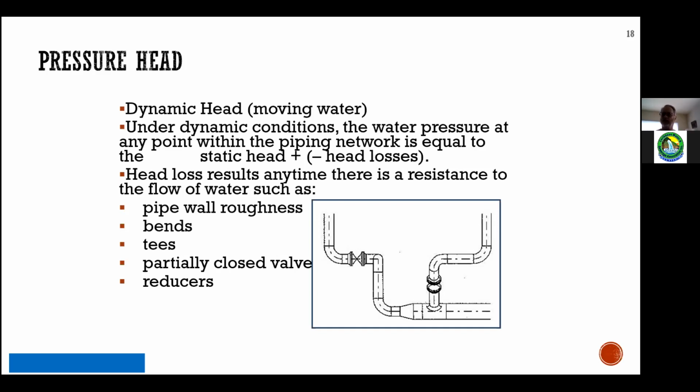So they thought that we had done something wrong when we tapped the main, that we hadn't tapped it properly, so there was no water coming out. No, it's simply too much head loss. And the American Water Works Association has all the tables in their standards to show different types of pipe, material, and diameter combined to create certain amounts of head loss per 100 feet or 30 meters of pipe.